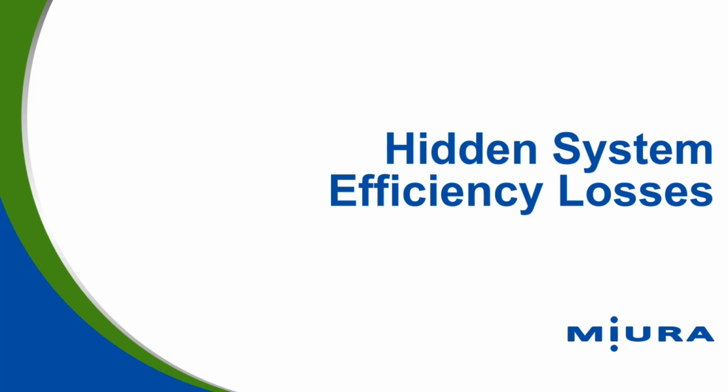Yeah, that's definitely going to have a pretty good impact. It's usually a 3 to 5% increase in efficiency when you add an economizer. So that's good. Okay. So next we're going to talk about some hidden system efficiency losses. I call them hidden because they're not included in that boiler efficiency number that you usually see from a manufacturer or from a spec or something.